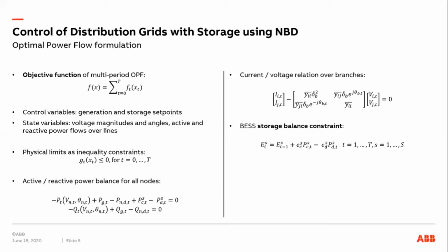This storage model could further be extended to add AC-DC converter losses, for example, and even to take into account the possibility for the converter to support reactive power for the voltage support ancillary service. Overall, the problem is nonlinear, non-convex, and at each time step there are linear coupling constraints between the time steps.